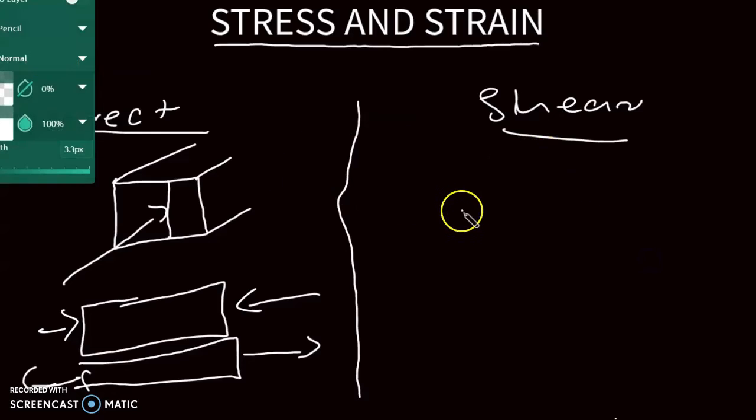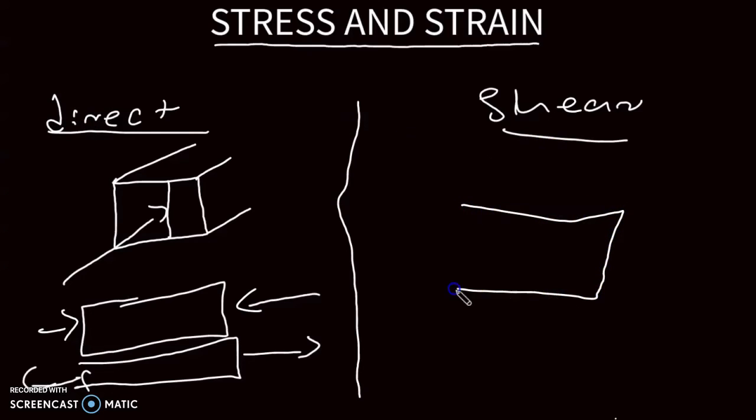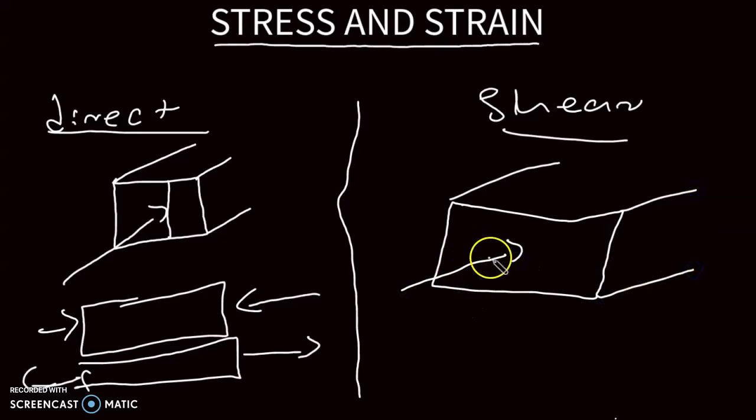The shear stress, let's use the same cross-sectional area. The shear stress, when it comes to the force that causes a shear stress, will not be perpendicular to the cross-sectional area that we are working with, but it will be parallel to the cross-sectional area that we are working with. So let's apply the same force here on this cross-sectional area. If we were to deal with this cross-sectional area, we are going to say this is a direct stress caused